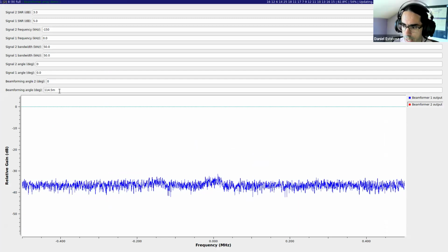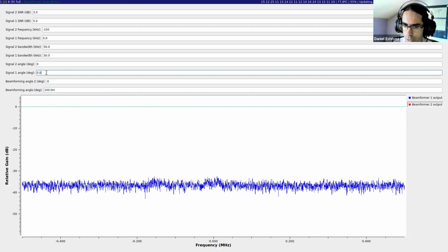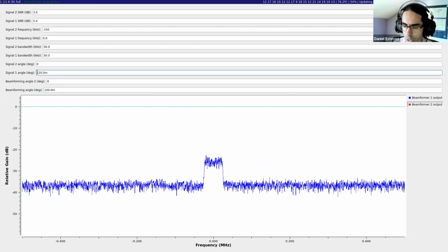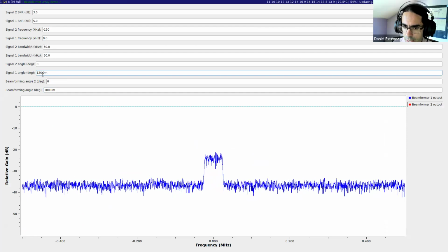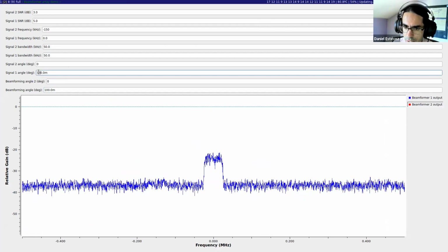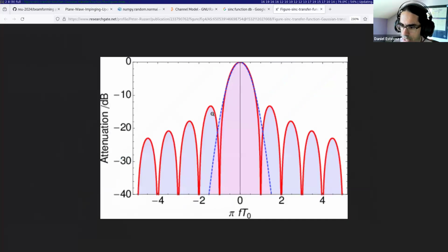So that means if I'm beamforming to 0.1, for example, and my source is 0.12, the angle error would be this 0.02. And this is the mathematical explanation for why we get this sinc pattern. This is how the Fourier transform enters the picture here.